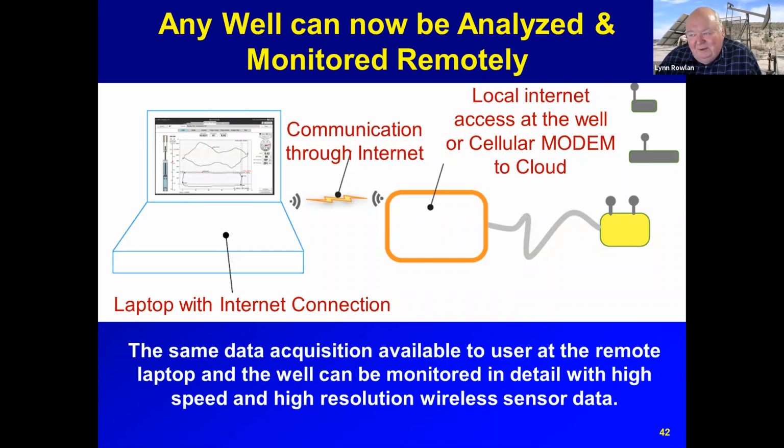But anyway, the Model H is designed for environments where there might be an explosive gas. If you go into an environment where there's hydrocarbon gas that could explode, you want the device to be certified to not create an explosion. That's called intrinsically safe. And so a lot of the Model H's are used offshore. They're used inside buildings up in Alaska, where the building's a confined space and explosive gas could collect in that space.